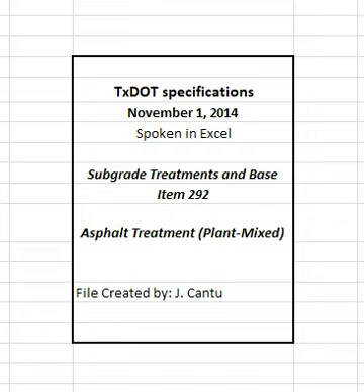Operate the augers at least 85% of the time. Keep the augers 1/2 to 3/4 full of mixture. Maintain an adequate flow of material to the center of the paver for the full width of the mat.